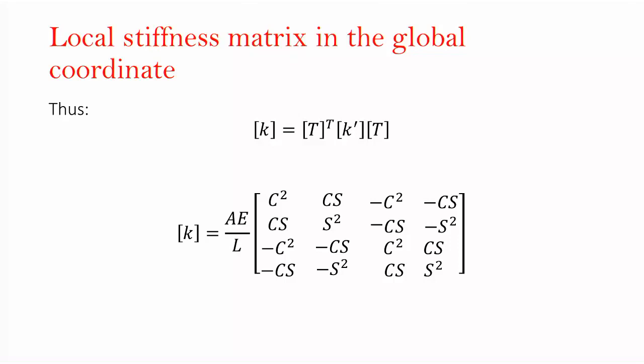We know that the bar element only has 2 degrees of freedom, so it should be 2x2. But when we convert it to the global matrix, we also have displacement in y and x directions at the same time. So that's why it would be a 4x4 K matrix.